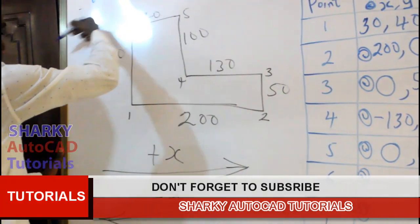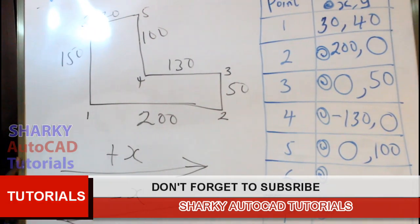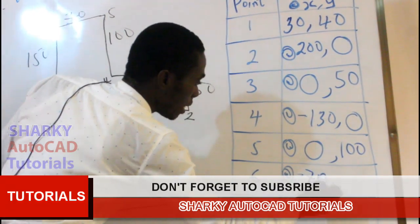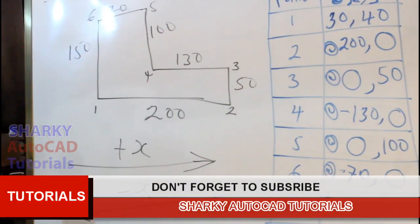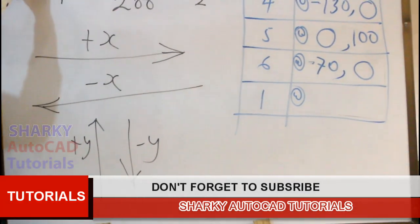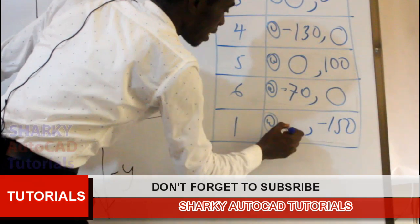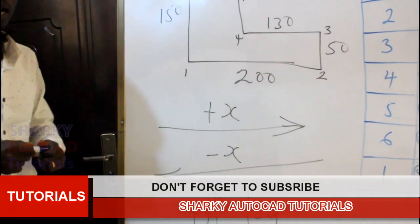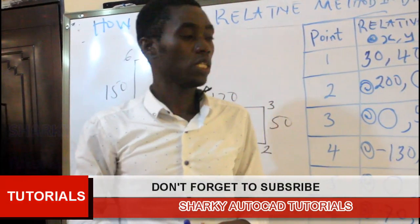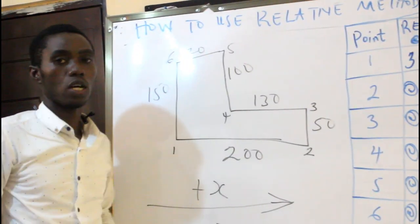And then at point 6, what direction is this? It is negative x, and the distance is 70. So over here you write negative 70, and then no y, y is 0. And finally, point 1. What direction is this? It is negative y, and the distance is 150. So negative 150, and then x is 0. So now, let's see how you can use AutoCAD 2020 and then input these coordinates to get the shape as you can see on the board.